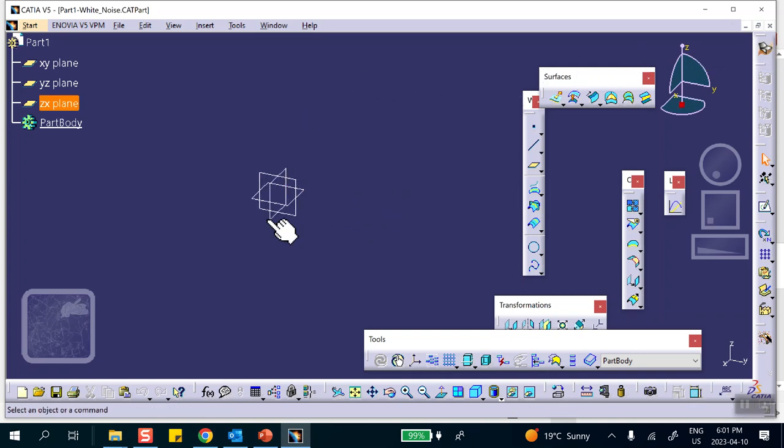Okay. So the spring, we're going to create it by creating two distinct points. One at 0, 0, 0. The other one is 1 meter away. Now, springs do not have length in practice, or at least in simulation cases. But here in Catia, it's strange, because we're going to need a beam element to be able to solve this simple single degree of freedom system. We still have to do an element, and the element happens to be a beam element, but we're never going to use it. There's certain things you have to do, but you're never going to use it.